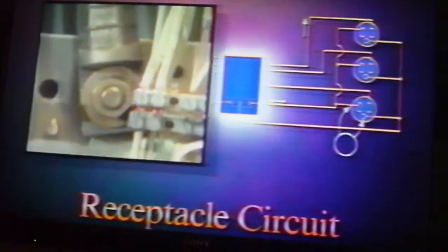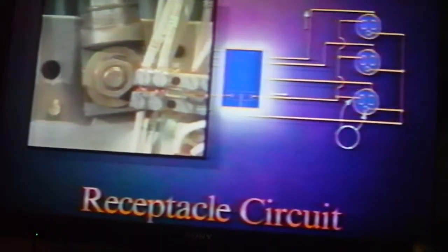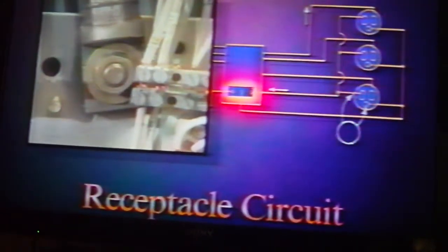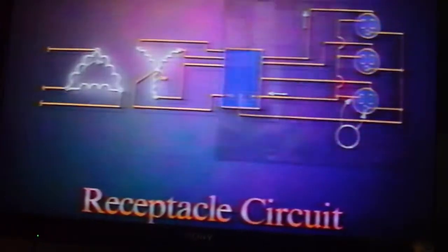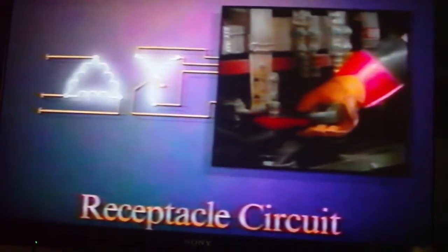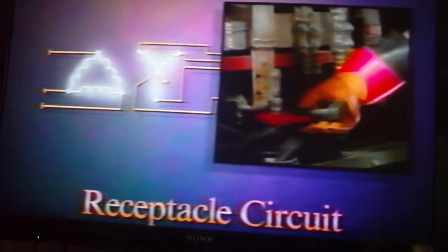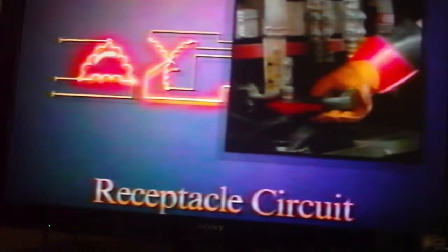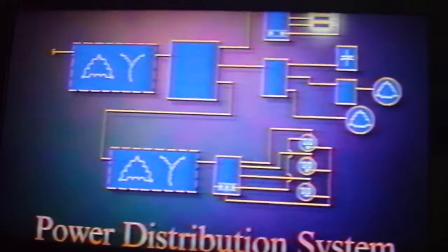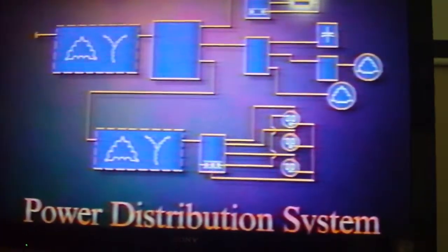Neutral bus bars and connecting lugs are sized to carry the full value of the rated phase current, but they can become overloaded when triplen harmonics add in the neutral conductors. Commercial buildings commonly have a 208/120-volt transformer in a delta-wye configuration, which feeds receptacles in the building. When triplen harmonic currents in the neutral reach the transformer secondary, they're reflected into the delta primary winding, where they circulate and cause overheating and transformer failures. The same type of problems occur in single-phase systems with lighting loads at 277 volts.